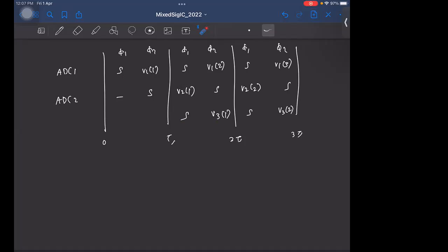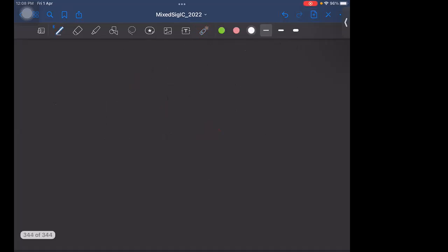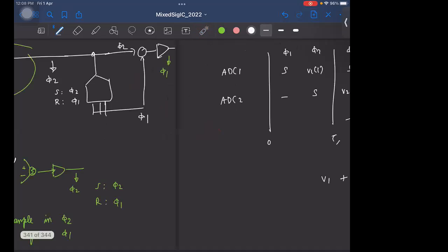Okay. So we find that the outputs of the individual ADCs are staggered by half clock cycle. So before you do the recombination with G1, G2, you need to make sure that all these are time aligned. That's all, right? And now, although we saw the circuit for only a single-ended version, for the differential version, you just have the same replica.